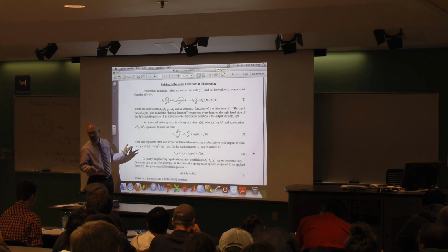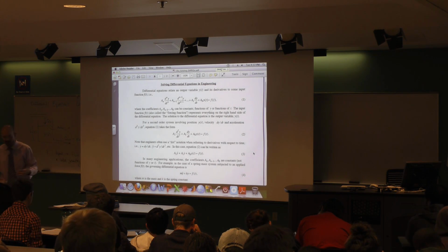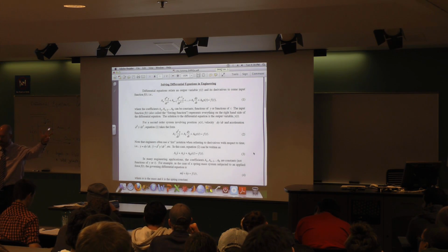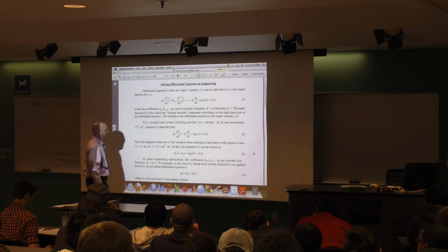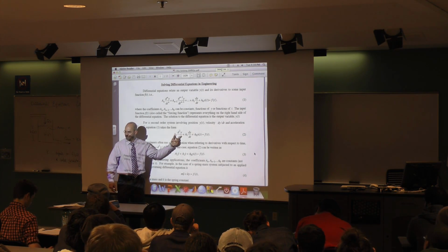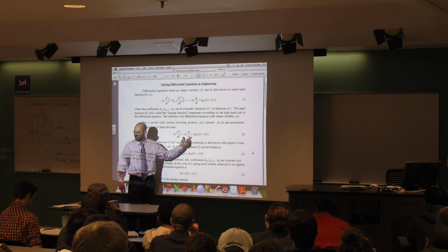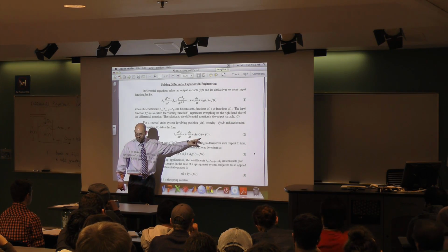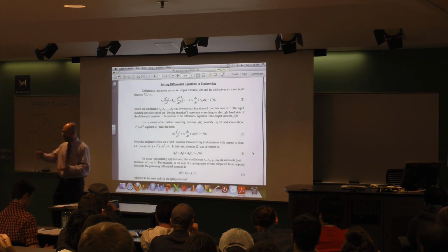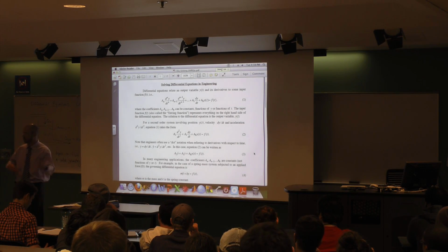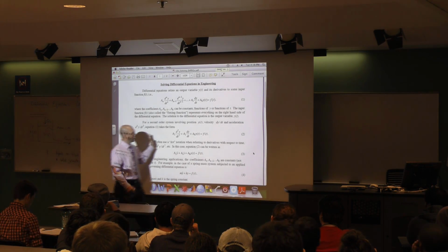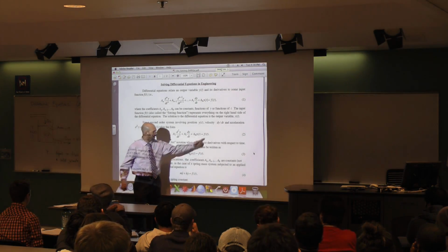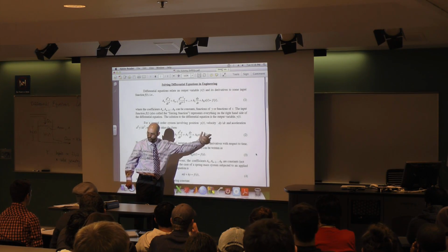So, for example, in a dynamics problem, we already talked extensively about this, all semester it seems like. Position, velocity, acceleration. Perfect example. Acceleration is the second derivative of position. Velocity is the first derivative of position. Position is the 0th derivative, the function itself. So the point is, if I have an oscillating system, something with a spring and a mass and a damper on it, then I would get this general second order equation here. And if I were forcing that with a literal force on it, that force would end up being the forcing function on the right hand side.